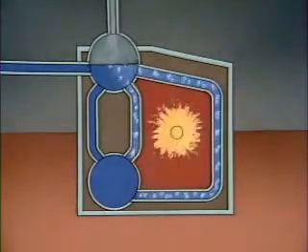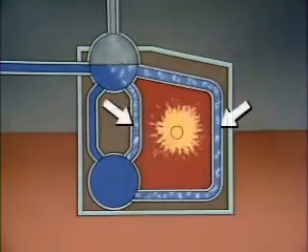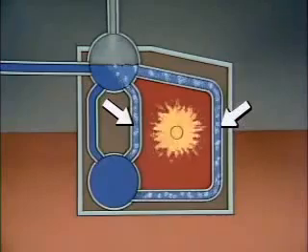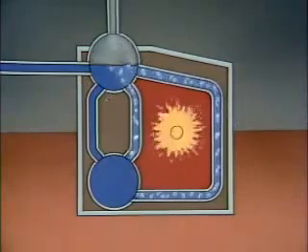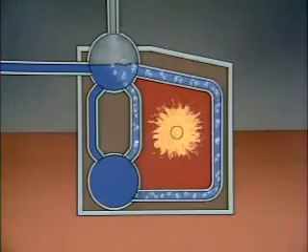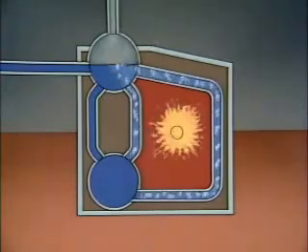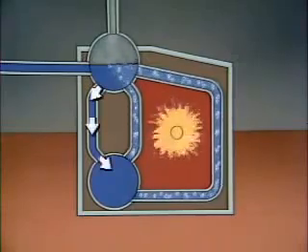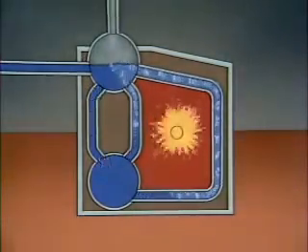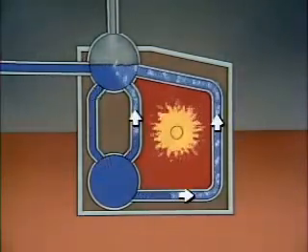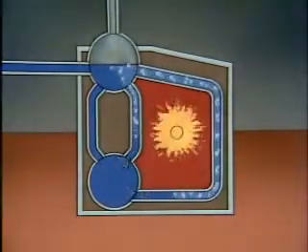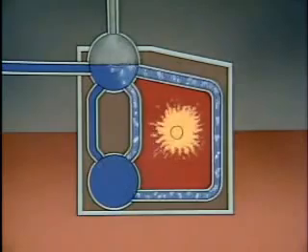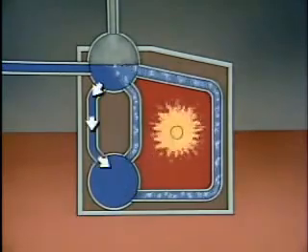As combustion occurs, the water tubes that surround the combustion area heat up. As heat is transferred to the water in these tubes, the water becomes less dense and lighter than the cooler water elsewhere in the boiler. Some of this water turns to steam. As a result, the heavier, cooler water flows downward into the lower drum, and the lighter steam-water mixture flows into the steam drum. Then, as the cooler water is heated, it too becomes lighter. It rises to the steam drum and is replaced by cooler, denser water.